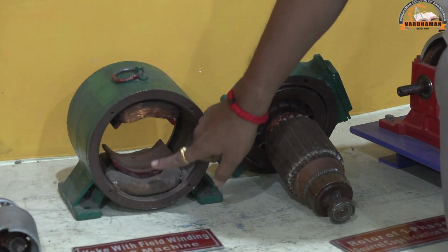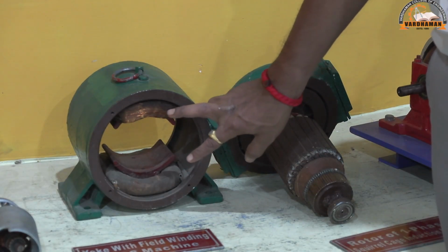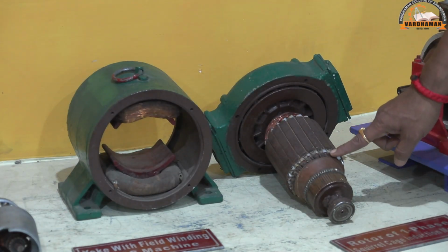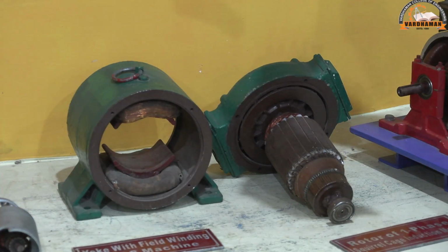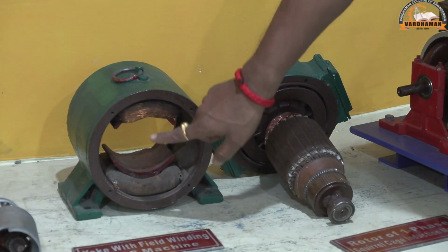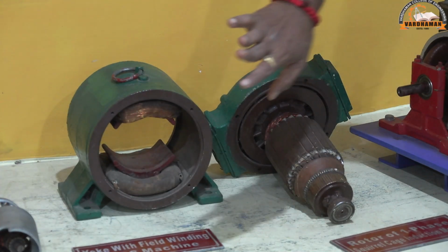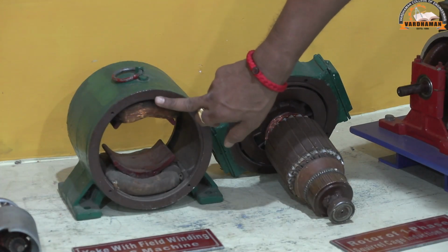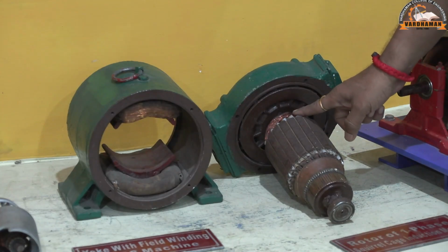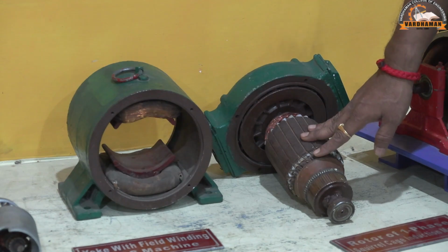The current which is given to the electromagnetic field coil is called excitation current. In separately excited motors, the current given to the magnetic field coil is taken from a separate source, and the current carrying armature conductors take their supply from some other source. So there is a separate power supply for the armature conductors and a separate power supply for the magnetic field coil. Such motors are separately excited, because they take power supply from separate sources, not from a common source. So this is given separately, this is given separately.